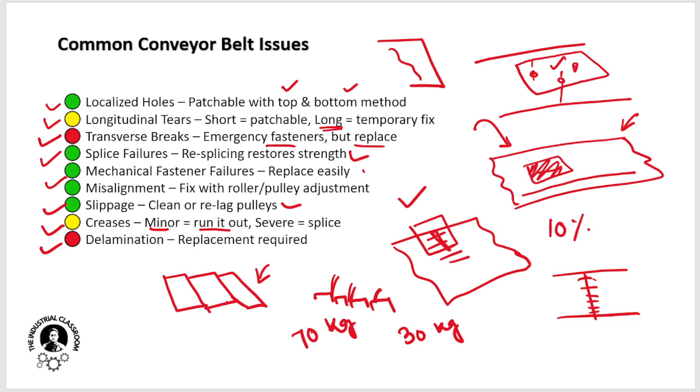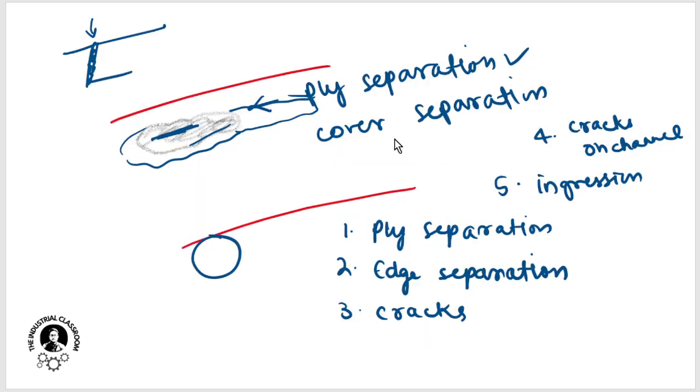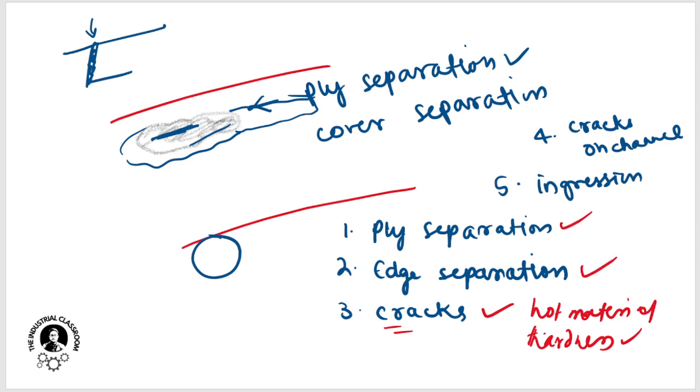Then there may be cracks, which I mentioned before. Cracks may be due to the top cover, where there is hot material. You have to move to some upgraded cover grade like UHR. You generally find cracks here, or an increase in the hardness of the belt. Then air separation and belt sway. These are some of the failure types.